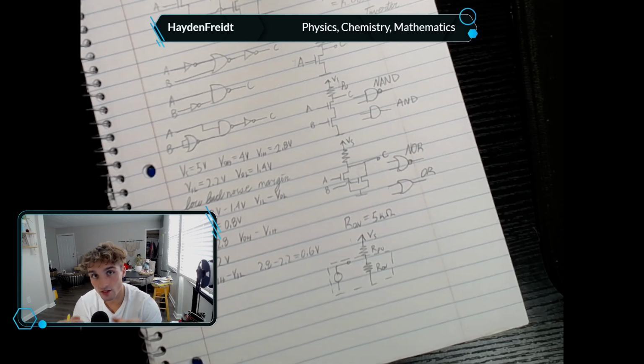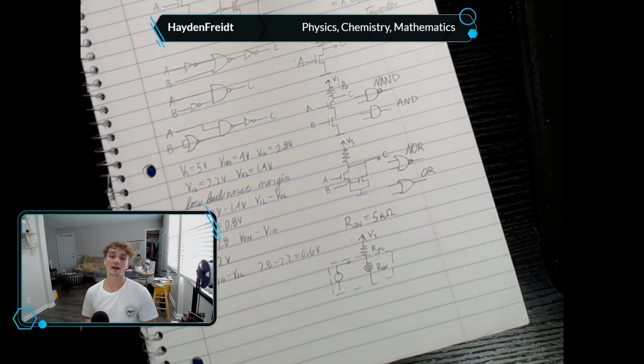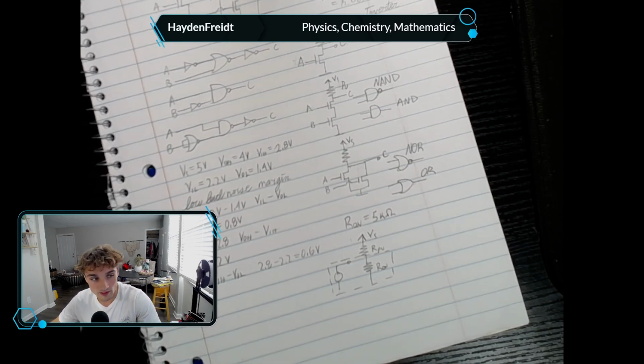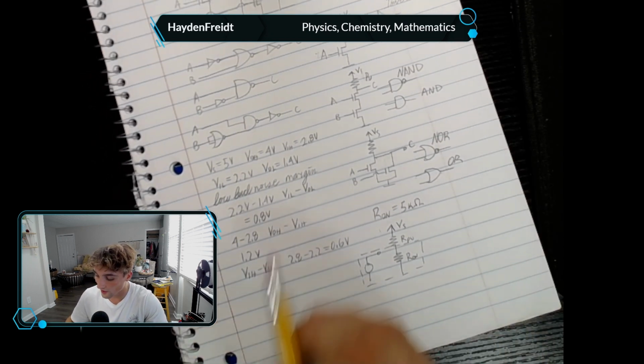With the transistor activated, meaning the gate source voltage is above the threshold voltage defined by the physical properties of the transistor, the switch resistor model for the transistor would look like R on equivalent to 5 kilo ohms, as given to us by this problem. So what is the minimum value that our pull-up resistor RPU can have, in kilo ohms, and still satisfy the static discipline which we defined right here?